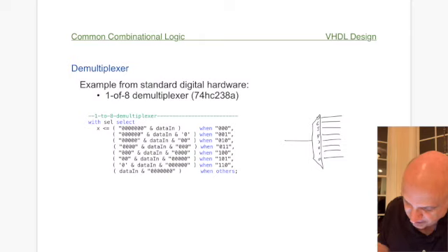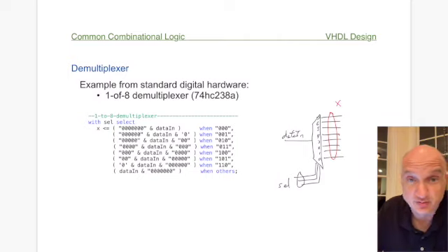And so basically, this represents, well, so we have to have our select lines here. All right. This represents the data in signal. These are the select lines. And this outer one here, all of these taken together, represent the output X, right? So in this case, X is a vector, and it holds 8 individual bits.